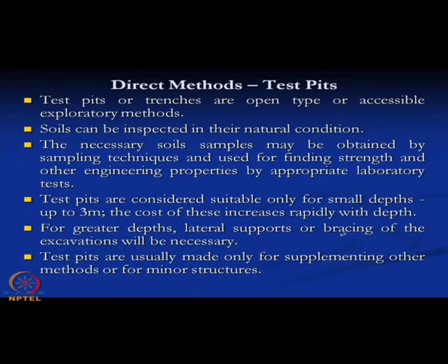So lateral support or bracing system will be necessary if the depth is high. So the cost will increase rapidly for a higher depth. So, test pits are usually made only for supplementing other methods or for minor structures.